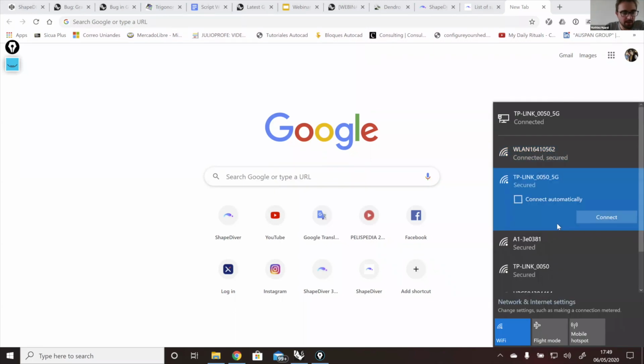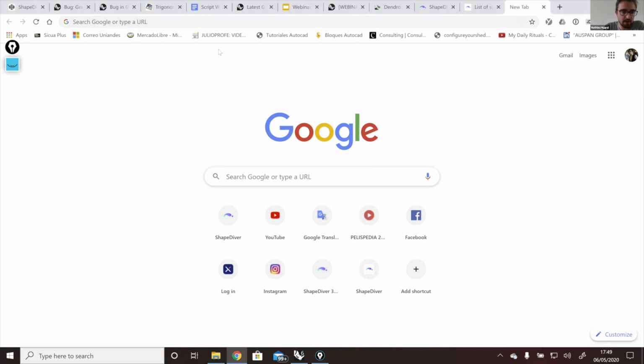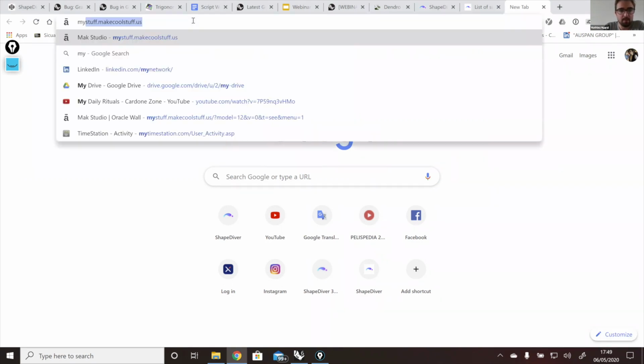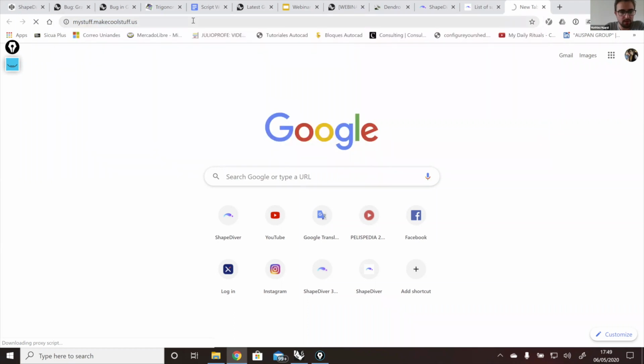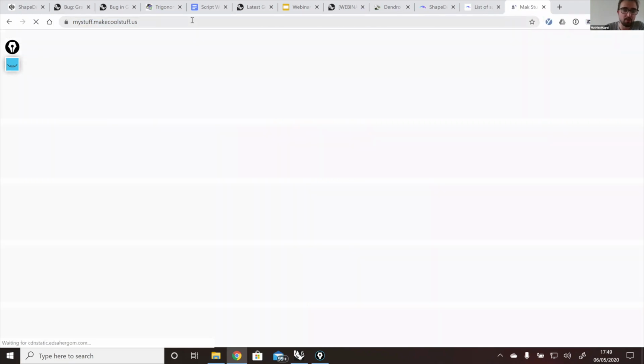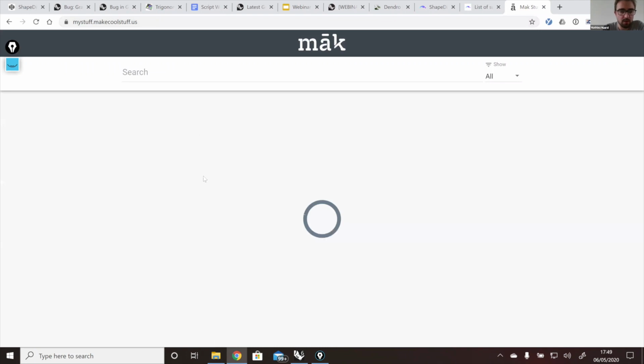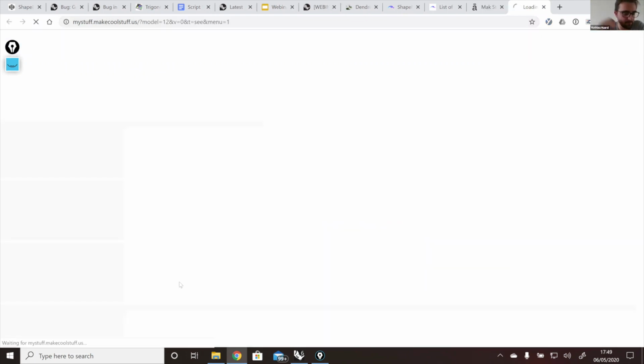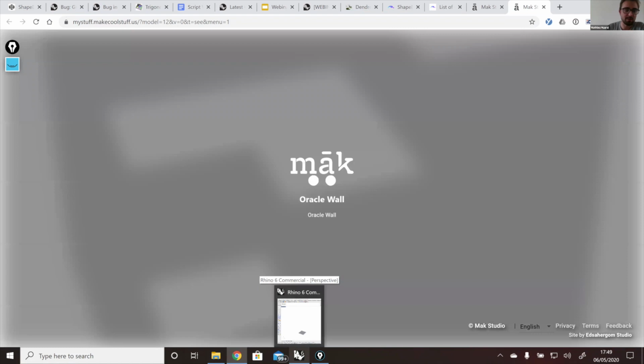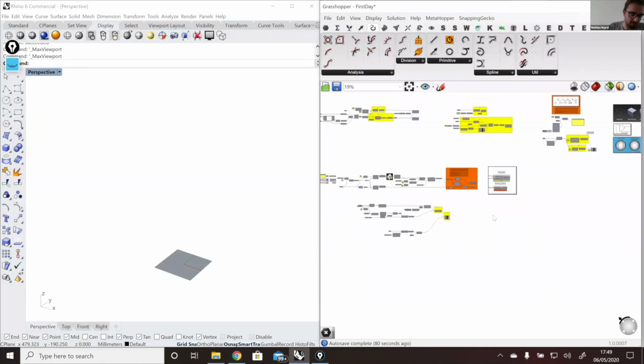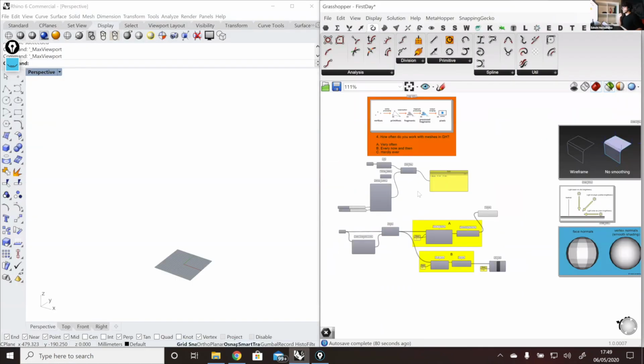Would the general guideline be to work with the simplest primitives, starting at number, math, point, line, and up? I mean, yeah, in general, right? I don't know what you would say, Edwin, but even the first example that Edwin showed, his latest version started with Brep, but you could also start by creating your own mesh, point by point. That would always be the most efficient. Of course, the complexity of doing that in most cases is very high. So as long as you can keep the simplest objects and work with them, that's great. But it's not always possible.